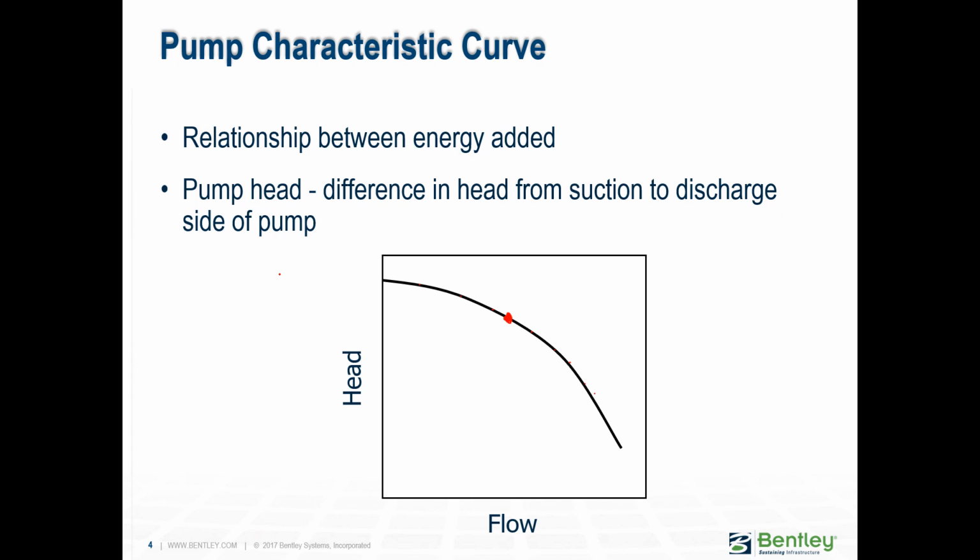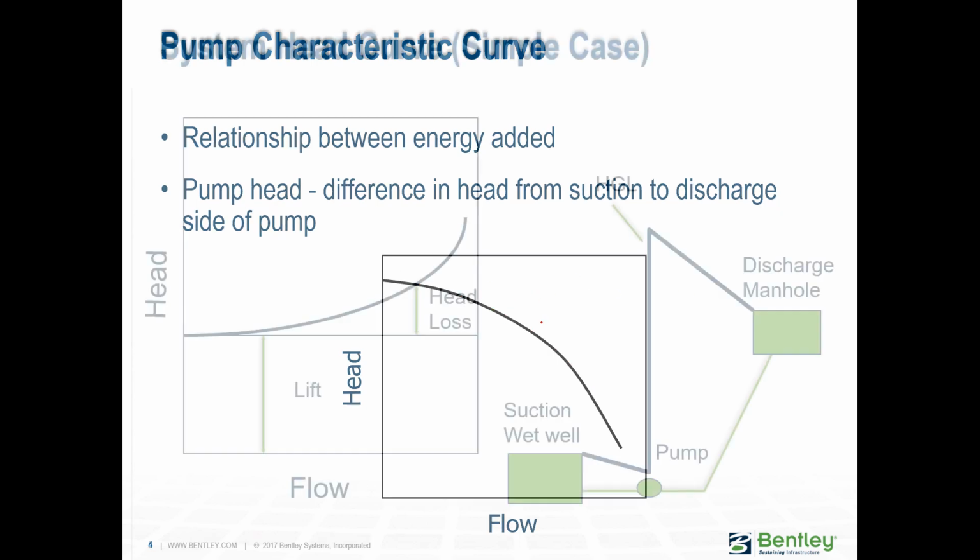So when we enter the pump element in SewerCAD, we just see one drawing of a pump, but really it's an element with a suction and a discharge. So in fact, when you look at the results, you can see what was the head at the suction and what was the head at the discharge end of that one element. And that is what is reported as pump head.